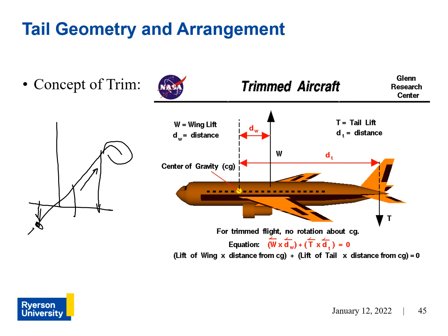And again, there's actually a mirror here where this is the stall region. And that's just for the reason that we want to have a negative lift so that the direction of the lift is down, and it counters the negative pitching moment about here, caused by the wing body / wing fuselage arrangement.